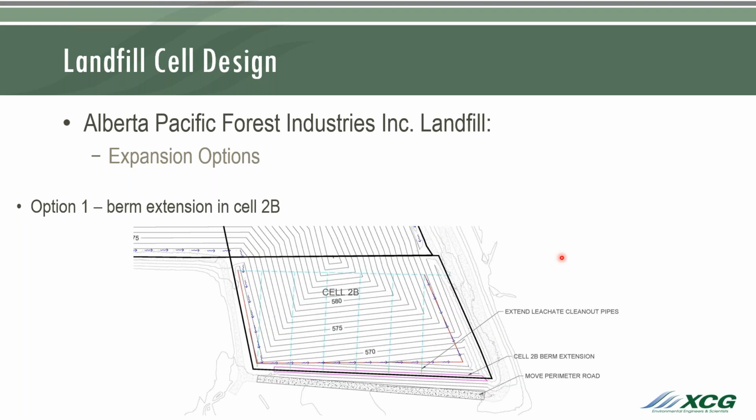So prior to deciding on the actual expansion, along with Alberta Pacific, we undertook some evaluation of different options that we could look at to possibly postpone the construction of the new landfill cell. One of the items that we looked at as part of that evaluation was extending an existing berm vertically and a little bit horizontally in order to gain us a little bit more airspace.